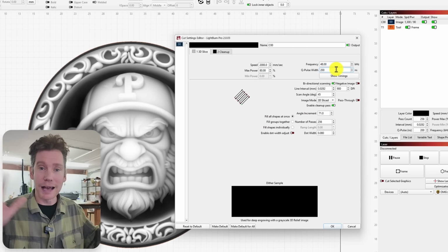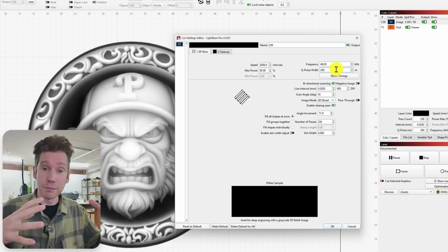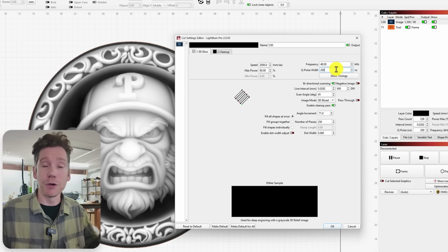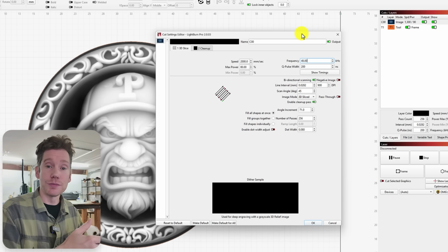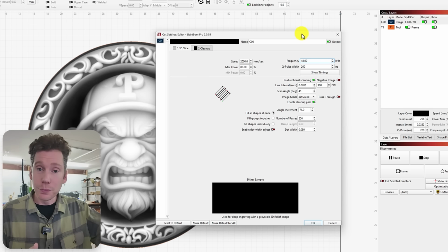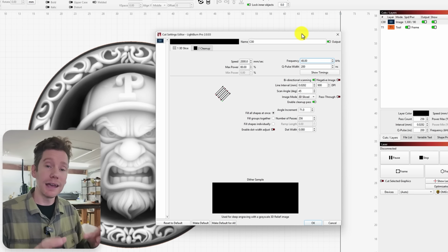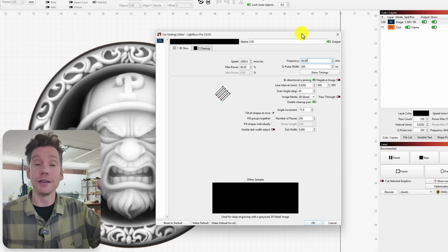So I don't want to blast your brains with any more information, but my laser and most MOPAs have what's called a cutoff frequency, which is your manufacturer saying, hey, any number that you choose below or above this cutoff frequency, I'll let you put that information into the system here, and I'll let you run it at that number, but I can't guarantee that I can keep the pulsing cycle stable,